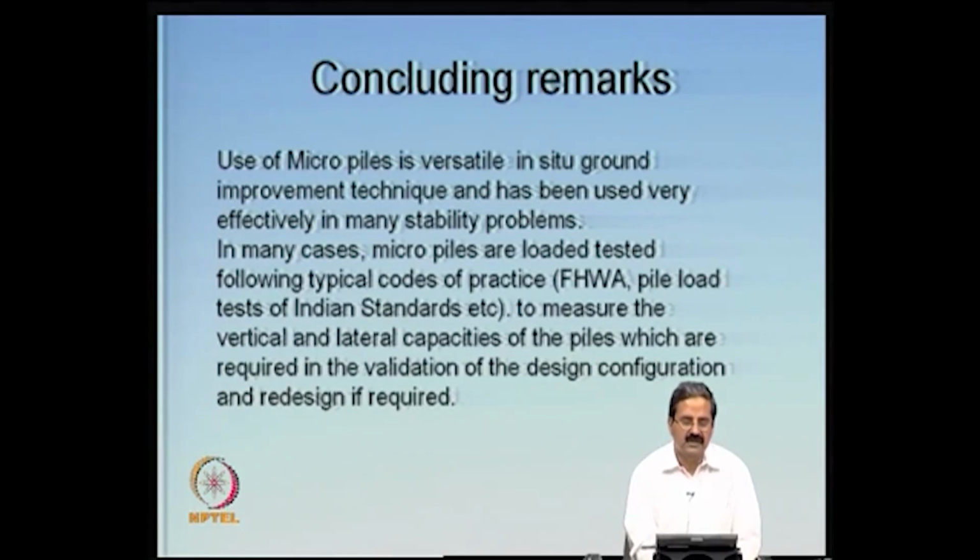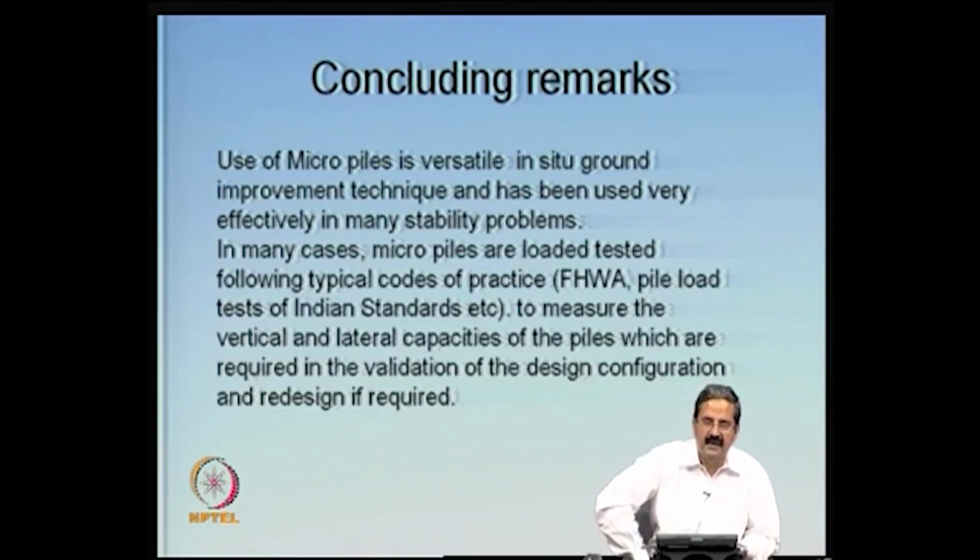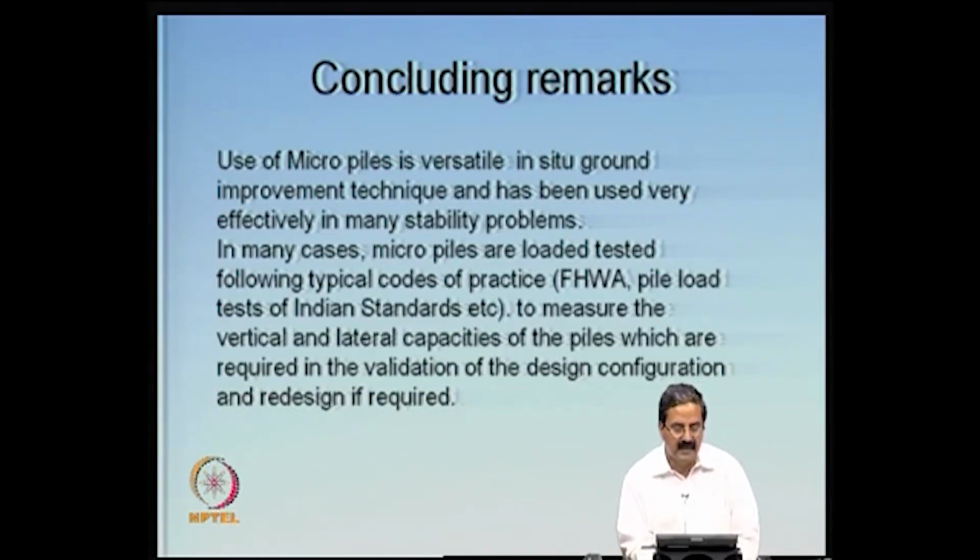So, we know this basic formula now, and we have seen how it can be obtained, from the skin friction of the pile and the soil, the pi d, and the length. Then some loads you can assume as vertical. If you are putting the pile vertical, that is fine. If you are putting it inclined, you have to take the normal component, and once you do that, it can be solved. Essentially, you are calculating the number of piles that are required.